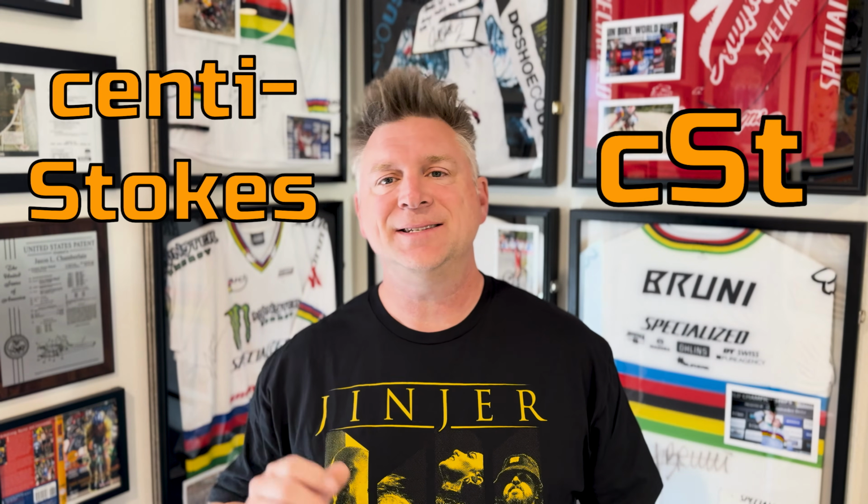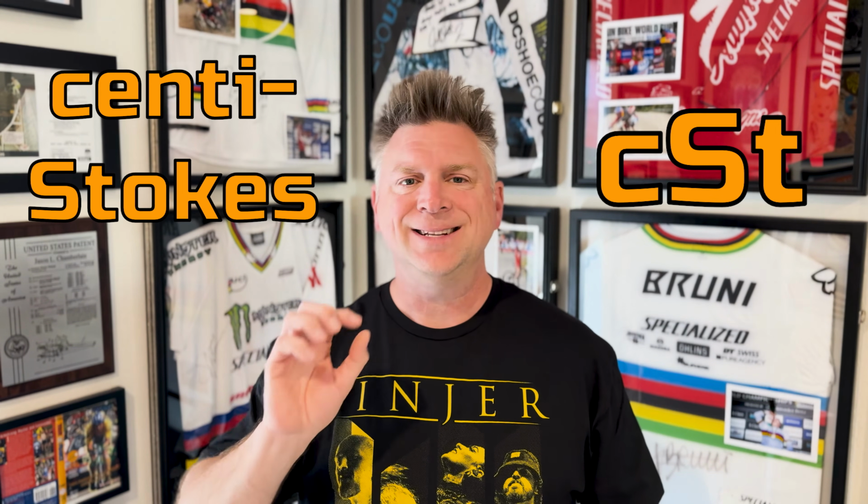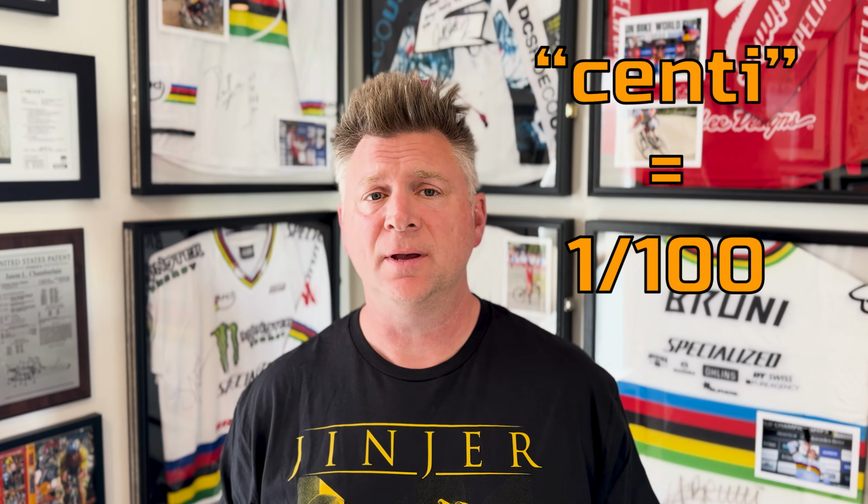The other measurement system is simply an international metric system, and the units are centistokes, or cSt. That's little c, big S, little t. The c is simply centi, meaning 1/100th, just like a centimeter is 1/100th of a meter. The other part is stokes. Just like meters, liters, seconds, stoke is the metric unit of viscosity. So why centistokes? I guess dividing by 100 simply makes the number on paper easier to use. Someone along the way thought it was easier to say 550 centistokes rather than 5.5 stokes.